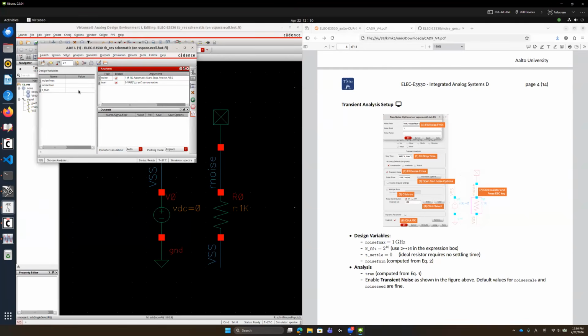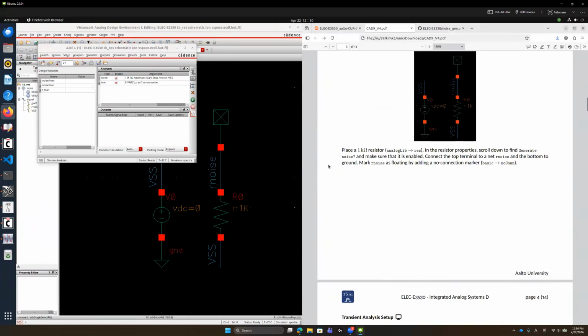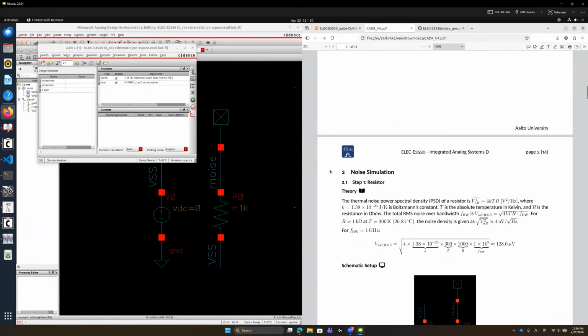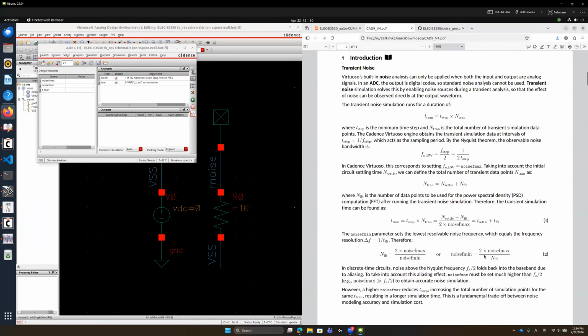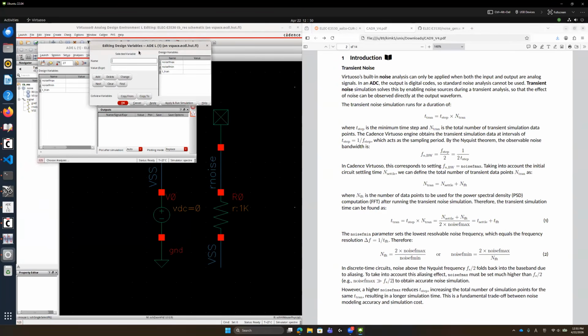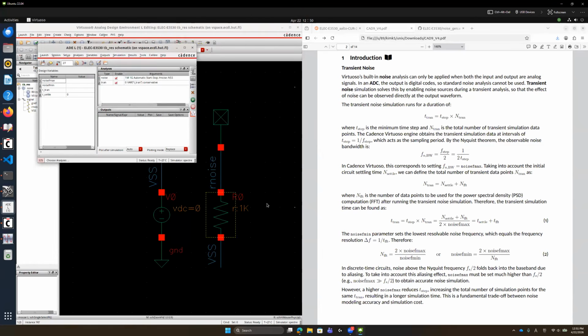And then yeah, so we collected here. So what you need to fill, according to this relationship, you need to fill this one. So let me define T settle first, which is settling time. In this case, we can assign just 0 because it's just one register. There's no such dynamic circuit or filter circuit, so it should not require any settling time for this register.